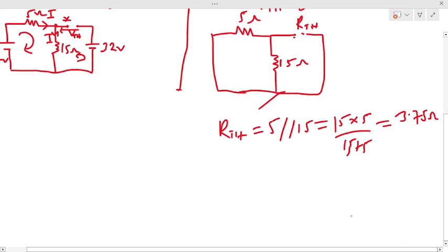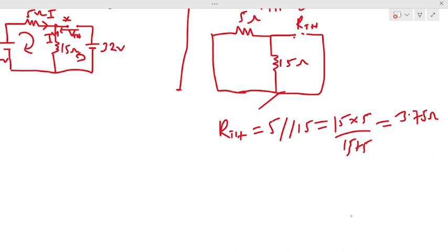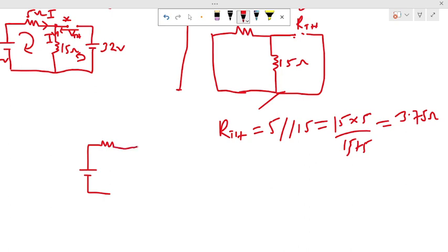Now we've gotten our Thevenin's resistance and the Thevenin's voltage. So as the law states that we can replace this linear circuit with a Thevenin's voltage in series with a Thevenin's resistance. So we redraw it to get a Thevenin circuit. So the Thevenin circuit, you can draw it as this. Now this portion will be the resistance that we are looking for. In this case, it is the 10 ohm resistance, and the Thevenin's resistance and the Thevenin's voltage will be at this portion.